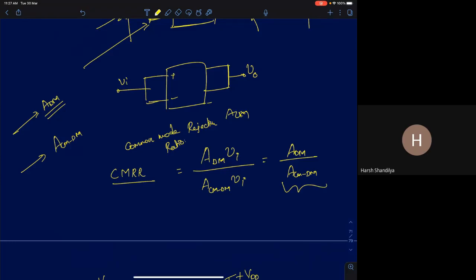To explain the reasoning, I said that in circuits or most analog systems, we define signal to noise ratio. In the same way, we can define signal gain by noise gain. It's not signal power, but gain. It's a ratio of two gains. It's not an SNR, but it's like an SNR. I explained the reasoning using the SNR idea, but this is not SNR by itself. It's just a metric to tell you how good your differential system is. SNR is a different thing.